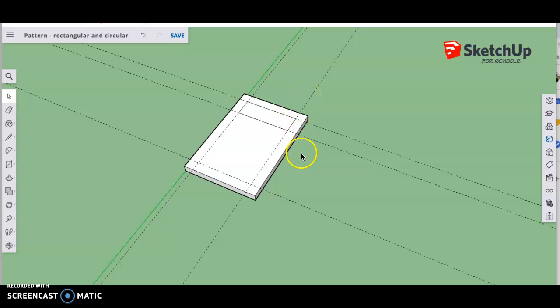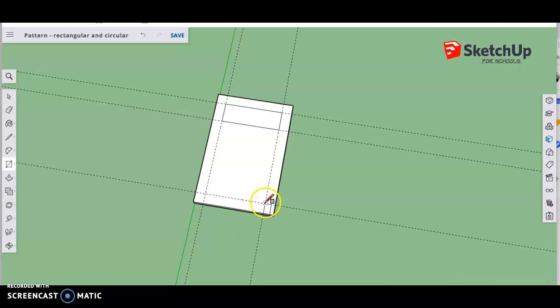The bell just rang. So I'm going to use my rectangle tool again now, and I'm going to make a little calculator key down here, and I'm going to make it 0.25 inches by 0.2 inches. And I'm going to press return, and there's my key. And I'm going to give that a little bit of thickness as well by doing a little push-pull, and we'll make it 0.1 inches high. There we go, very small.